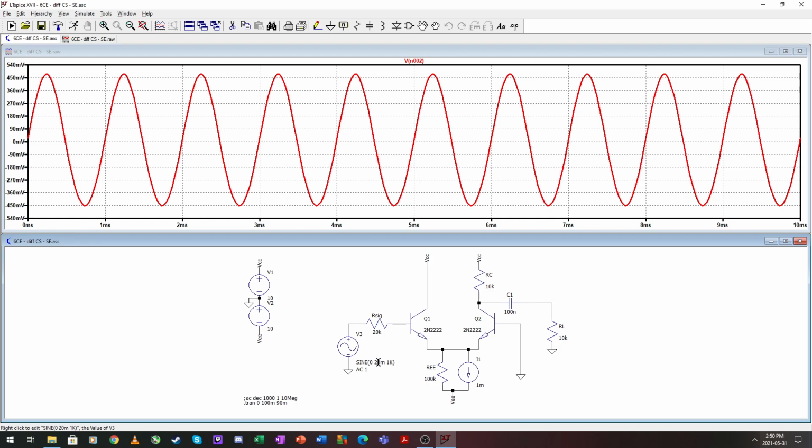So 200 became 100. Sorry, 20 millivolts times 100, which is half the gain, is 2 volts. If we half that, it is 1 volt on the output. If you half that due to the input impedance, it is in the range of 500 millivolts.